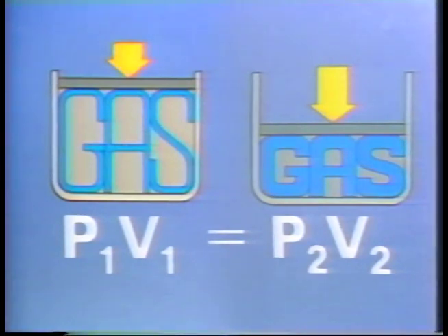The pressure used for P1 and P2 must be in psia. If psig is used, then the answer will be wrong. Remember, to convert psig to psia, add atmospheric pressure to the psig reading.